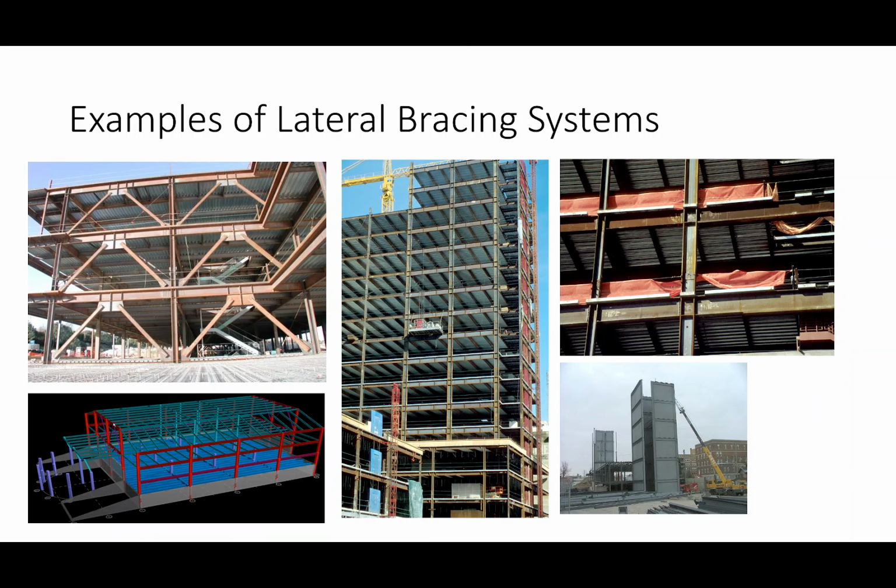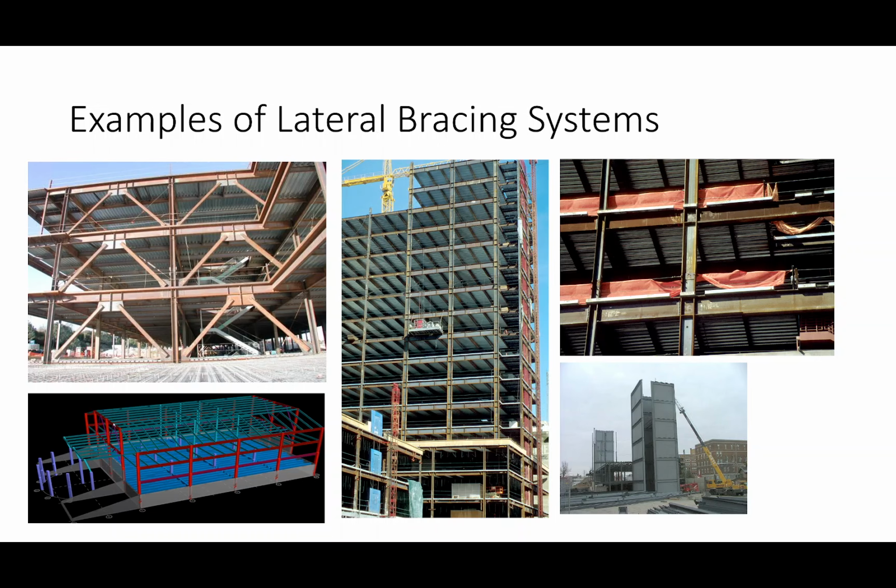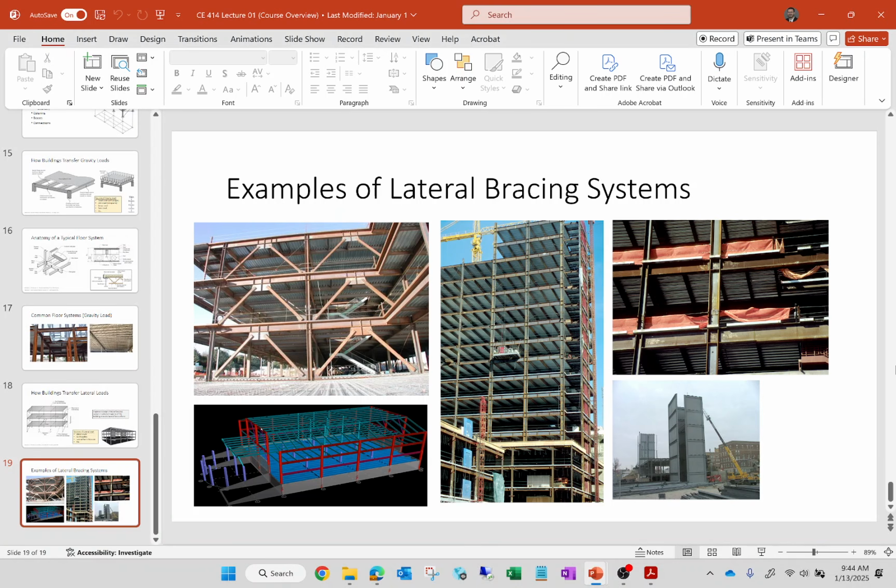You can also use shear walls. Shear walls are also an option. You literally just fill in between a beam and a column, either with concrete or a steel plate. Not as common as brace frames or moment frames, but again, an option. I just wanted to put a bunch of stuff in your head as we start talking about this throughout the semester. Does this all sound fun?